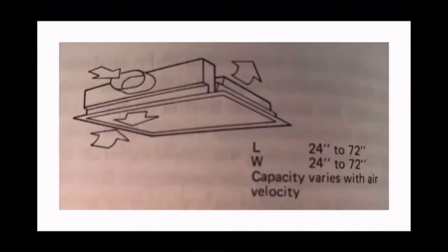Now there's another version that's also in Mead that talks about warm air going in as a supply, and then coming out and being heated. And this is for a cold climate or a cold season. So if we're bringing hot air into a space, the idea is again that we could run it across a light fixture, and take some of the heat from the light fixture and use it to reheat the air, because maybe it's lost some of its punch as it moved from the air handling unit and got cooler as it moved through the building before it hits its eventual diffuser. But in reality, again, these are kind of dated ideas and are really no longer relevant.